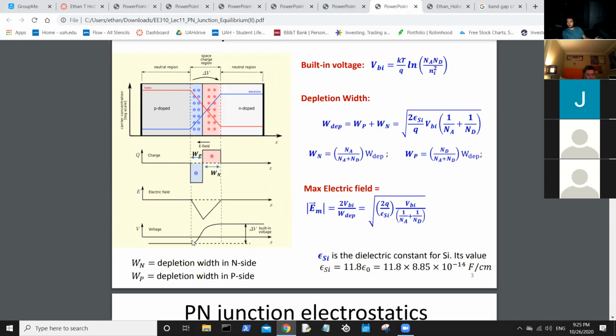That's 2/3, or like 0.666. So what you do is you simply take your ratio at your given point. It's asking at the junction point. So that's why we start at 0 and calculate up until the junction point, which means we're calculating WP. You calculate WP, it happens to be 2/3. You multiply 2/3 by your built-in voltage, which was given to us as 0.9 in the question, because that's what the difference in potential is, as illustrated in this figure. When you multiply it there, it's going to give you the voltage at the junction point, which is some intermediate value between 0 and the built-in voltage, which for our case was 0.6.